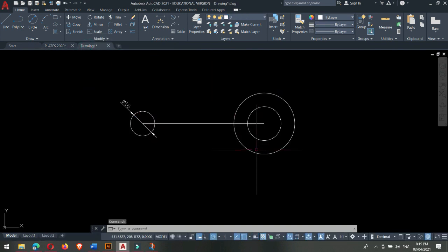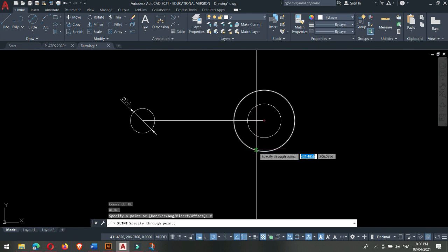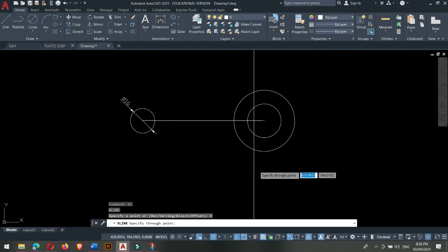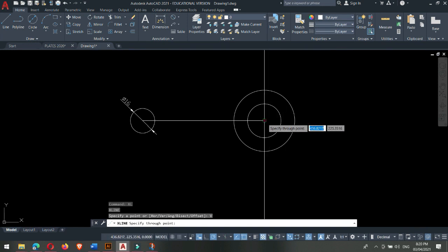Okay. So I'm gonna create a construction line. A construction line is a line that is extended towards the whole AutoCAD drawing. So how to do the construction line? I'm gonna hit XL on the keyboard. That's the shortcut. X line, XL, enter. And I need a vertical one. I'm gonna type V, enter. And there it is. Now there's a construction line that extends to the whole drawing area. So I'm gonna drop it here, left click, and escape.